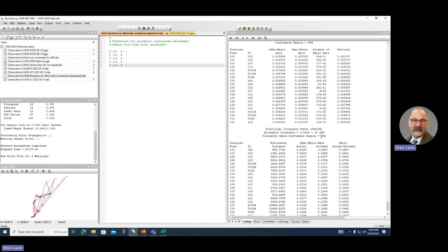Okay, the specs for azimuth pairs say you have to have 2 vectors between them. So those are required. And then, like that. If I ran 4 receivers, I could get, for 2 sessions, 6 baselines. I would get this exact minimum amount of baselines, 1, 2, 3, 4, 5, 6.